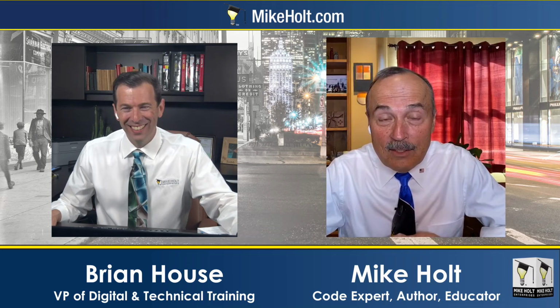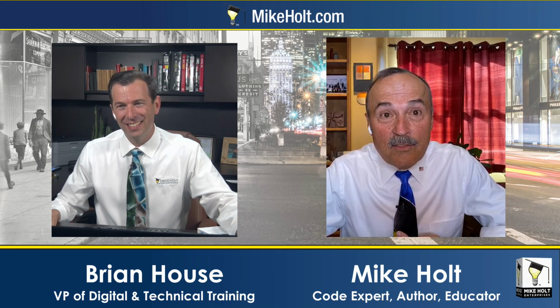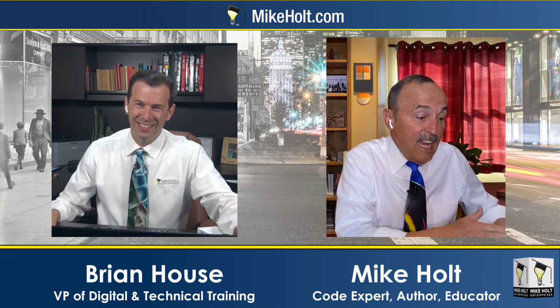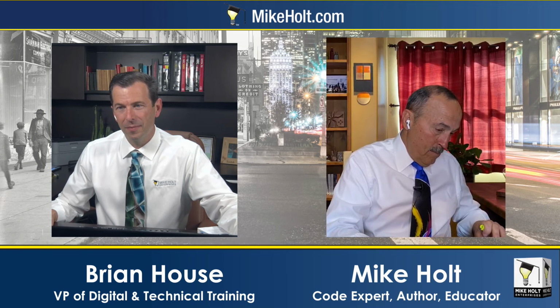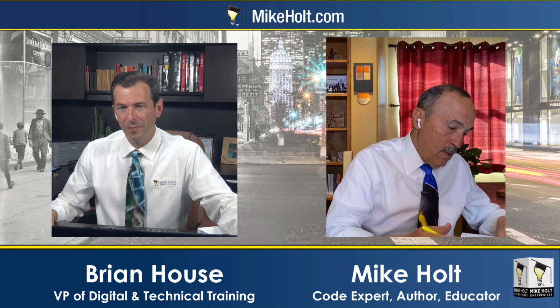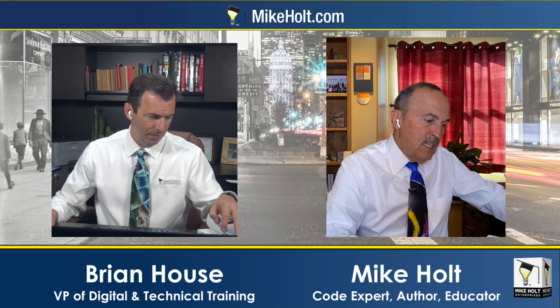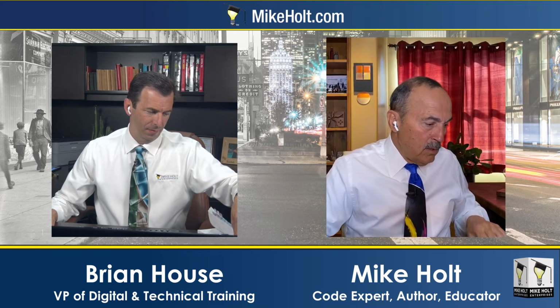But let me give you guys a little suggestion. I thought 314.30(D) applied initially. Okay, now let's go back to 314.30. If this was a handhold, which it is not, and it doesn't apply, you would go to 314.30(D). Actually, 314.30(D) only says you have to have a lug. That doesn't say you have to connect anything to it. Let's see if there's a rule somewhere. Yeah, it just says you have to have a lug.